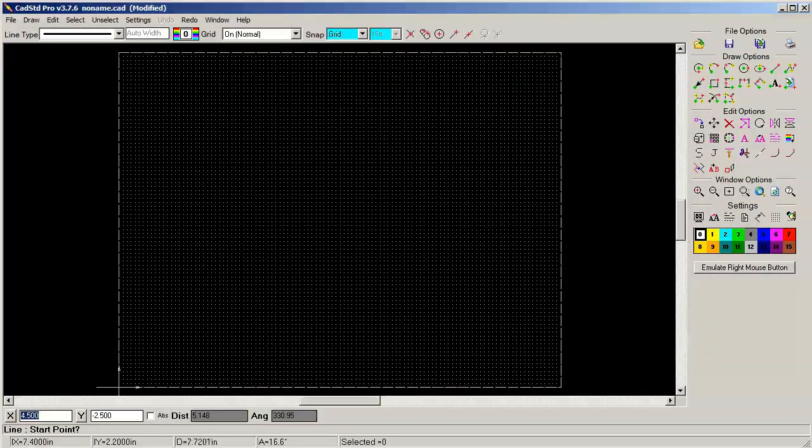Click Draw, select Line. After choosing the line tool, click on Grid at upper left area as shown to start the line. Left click at corner spot, move down, left click again, move left to grid line where you started, left click again, and finally move up to starting point and left click. Now you need to right click to end the line creation command. You created a closed box, a front view.